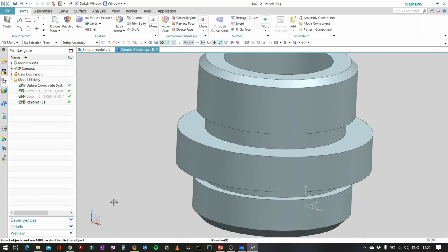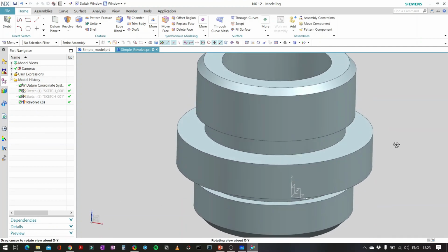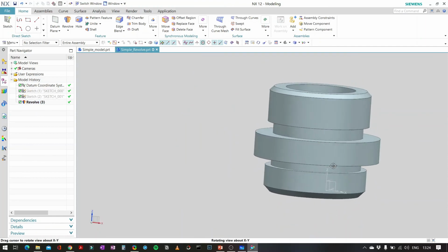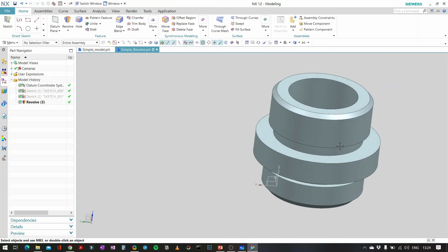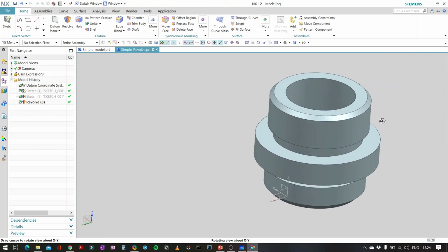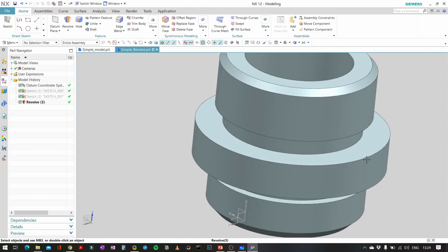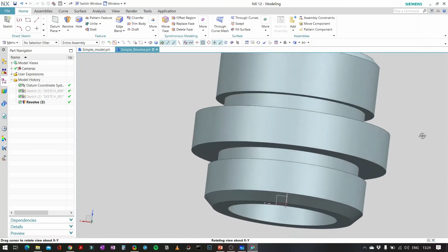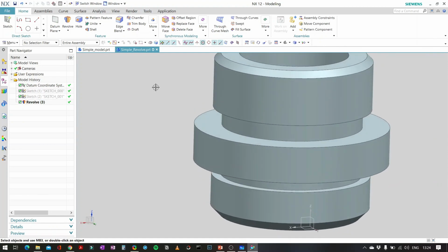Now in practice, we'll not be able to manufacture exact curves, so some chamfers would definitely be given in the manufacturing drawing. So the manufacturing drawing is different from the design drawing. It would have certain things which are specifically relatable for manufacturing that particular component.